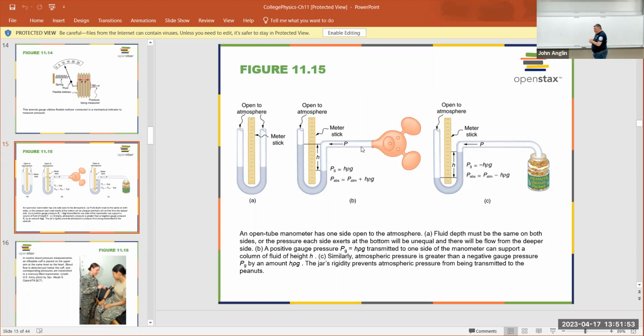And since it's an enclosed tube and it tries to expand, that means it has to increase the pressure, which means the level of that fluid must change. And those things are calibrated to say, oh, a change of 2 millimeters is 1.5 degrees or something, whatever it's calibrated to. So that's how those thermometers work, on exactly this principle, except we're not using mechanical means to increase the pressure. We're doing it with thermal energy.